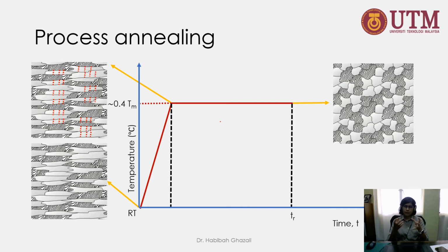And as we've learned from solidification, as the new seed is formed, other atoms will start to latch themselves onto that nucleus. This can happen because we have increased the temperature. Atoms are mobile, they can diffuse, and they will arrange themselves onto these new seeds that are formed in various locations of the grain.